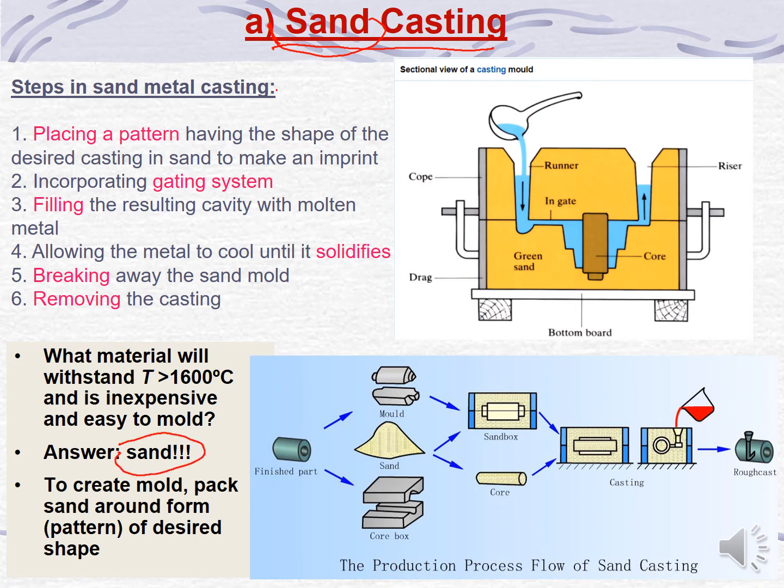Why sand? Because sand can withstand high temperatures, more than 1,600 degrees Celsius, and is inexpensive and easy to mold. Inexpensive means that the sand can be recycled.